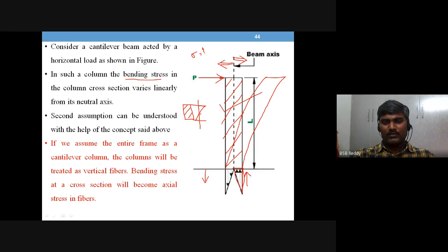You observe these two triangles here. This triangle is the compression triangle, and this is tensile. Here also you have two triangles, but one on the other side, the other on this left side, on either side of the reference line. Here you can follow the same side of the reference line and note that this is some tension and this is some compression. That can also be done. But this is the general way of drawing this for beams, and for columns we follow this way.